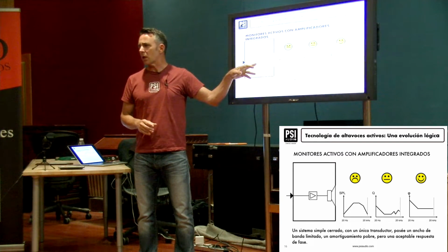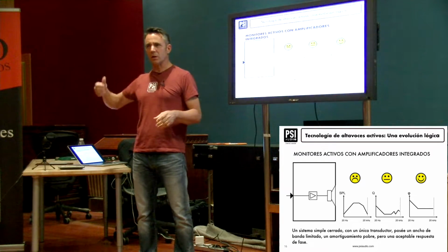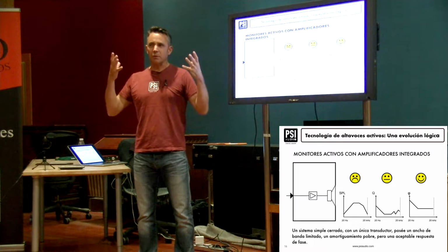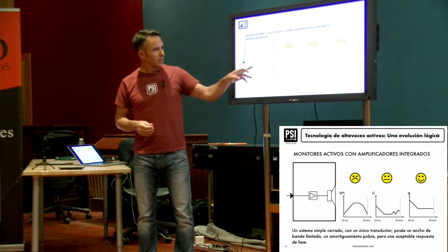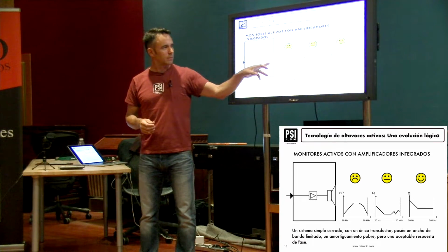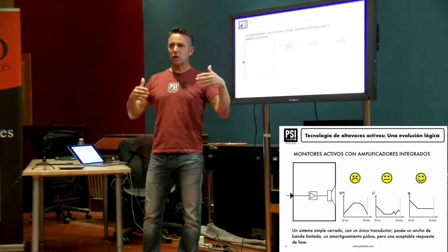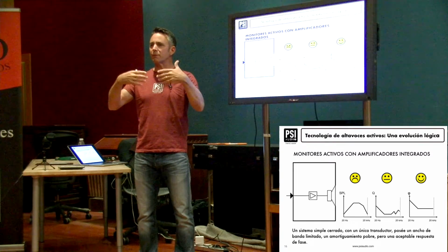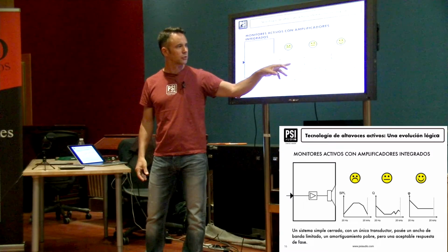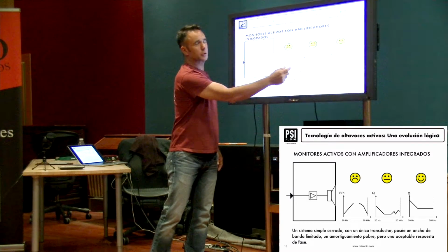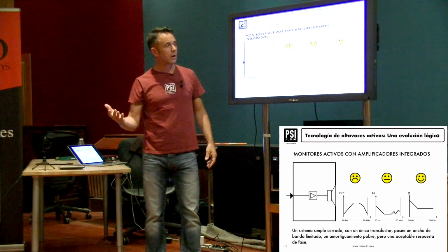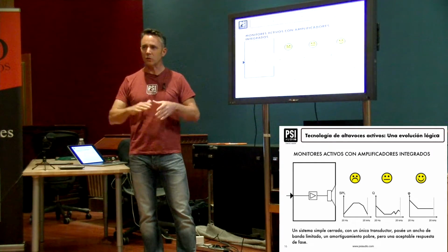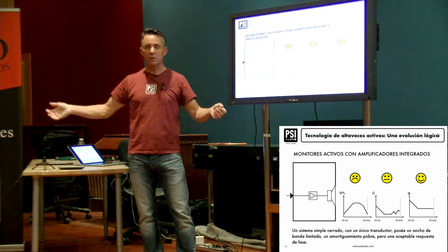This is like when you buy a car, the engine's in the car. You're not going to buy a car and then buy an engine that's trailing 100 meters behind. So that's the idea that we have. And then you can adapt it to this membrane. And this membrane, as we saw, is a mobile mass on springs. And of course, it'll move differently at different frequencies. So each one of these drivers will be quite good at reproducing a certain range of frequencies, but not more than that. And then there are the mechanical filters that roll off the low ends and the high ends.